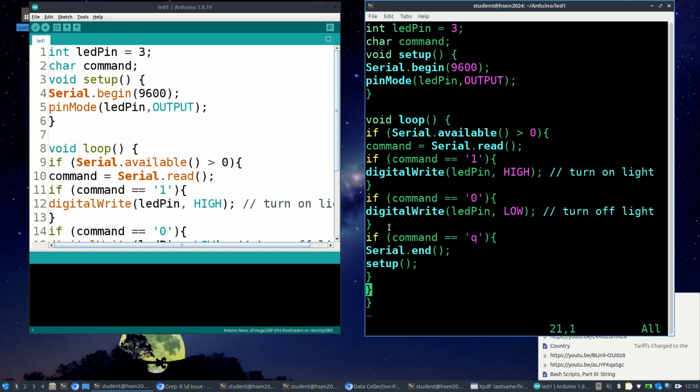And then from that row, you need to run a wire to ground. Okay, so the circuit looks like this. You've got your Nano, D3 here, connected to the 270 ohm resistor, connected to the LED, and then over to ground. And I'm happy to look at anybody's circuit if they want me to, okay?